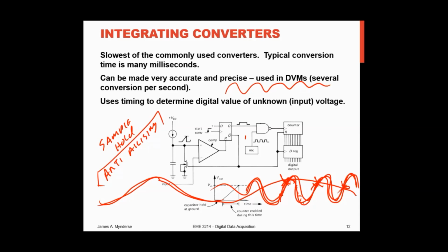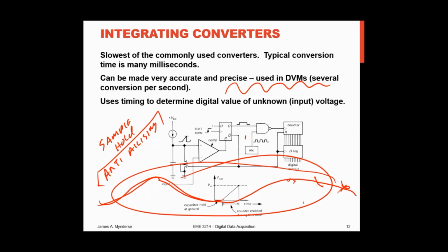Instead of seeing this high frequency signal, you're going to see this low frequency signal, and you're going to say, oh, well, the car is floating up and down, there's something happening, and you try and tune your suspension to get rid of this signal here, which didn't exist, right? And it's just not going to work. And it's been done, and people make this mistake. So you really want to understand the pitfalls of this conversion from analog to digital world.